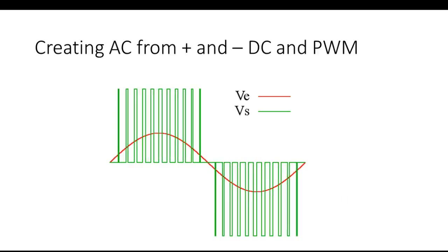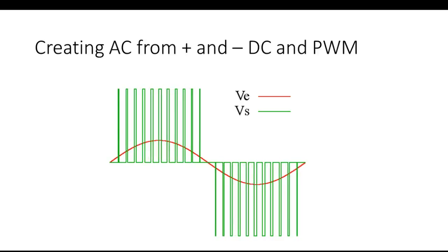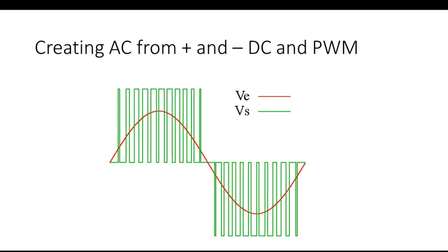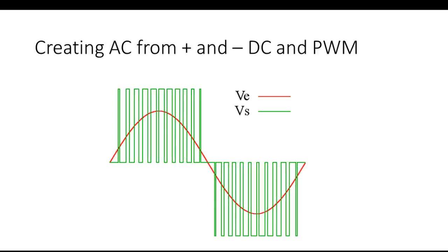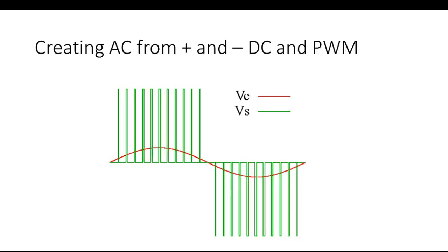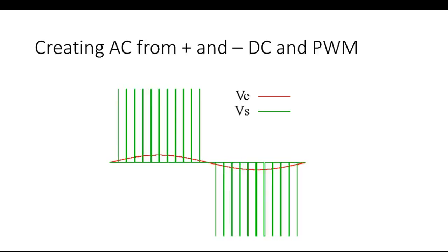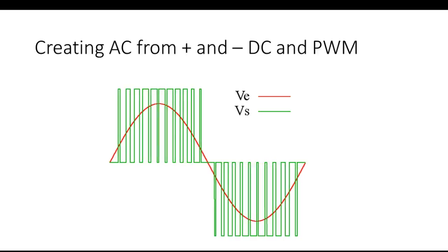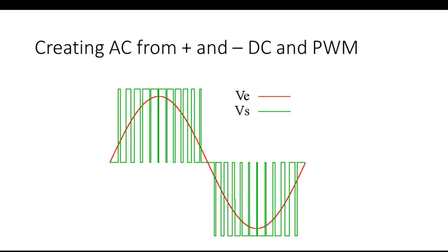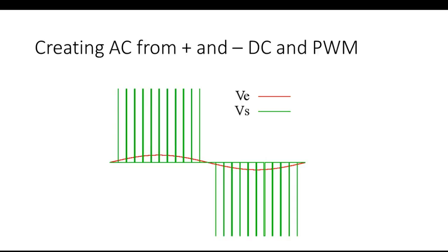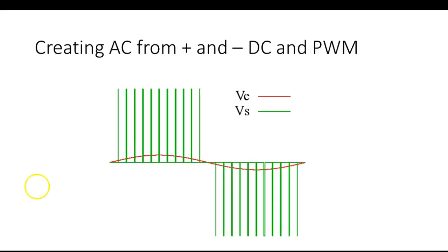What they do is they use a technique called pulse width modulation. Notice what they can do. Not only can they change the voltage, but if they come in and start reducing the width, what are they going to do? They're going to change the frequency. So normally these things use pulse width modulation. Variable speed drives. I couldn't find one that changed the frequency, but I thought this was real neat. Your AC motor will see this. Your AC motor's got a big inductor on it. We won't quite see that. If we fed this thing directly to it, we would end up with a